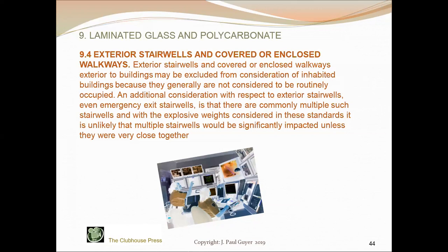Also, stair structures are commonly of robust construction, and even though they do not require compliance glazing, it's likely that they will still be usable even though they are covered with broken glass. Standoff distance, therefore, may be to the walls of the buildings instead of the walls of the exterior stairwells or covered walkways.